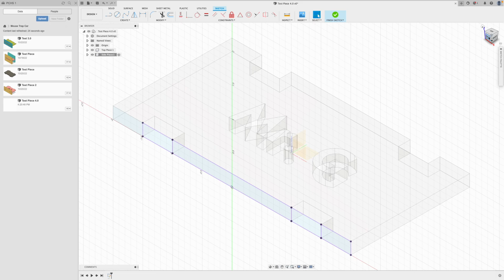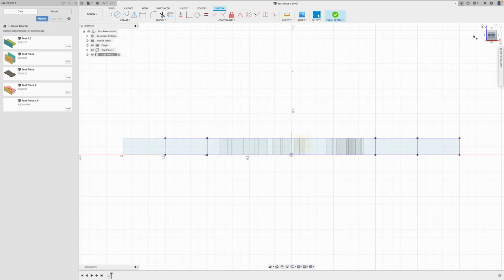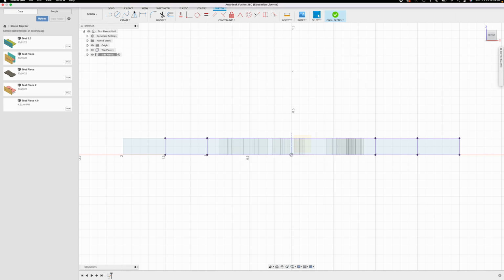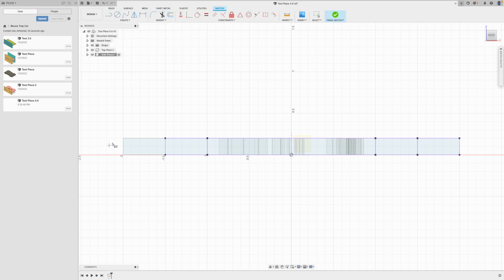Then I'm going to draw here on my front view. So front view up top here. I'm going to draw a rectangle. So a 2-point rectangle. R is your shortcut for rectangle also. You're going to click across, drag, and I'll escape here. Something happened. R, rectangle, R, and let's see if I can click on this corner here. There we go. And going right to here. Let's try one more time here, and then if not, I'll redo this video. All right, rectangle right there. And then I can drag all the way across there. It locks on that point here.